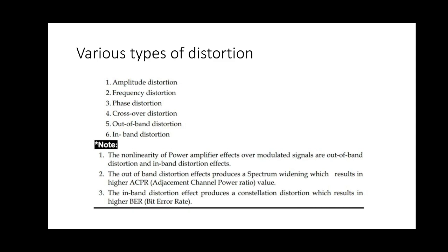Many of the input signals that a practical amplifier will amplify consist of the required signal waveform, called the fundamental frequency, plus a number of different frequencies called harmonics superimposed on it. New frequencies are produced in the output which are not present in the input. The shape of the output signal is not the same as the input, called harmonic distortion. Phase distortion is caused by different frequency components undergoing different delays in the process of amplification.